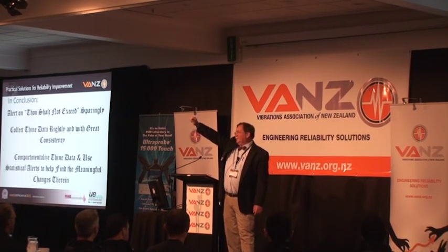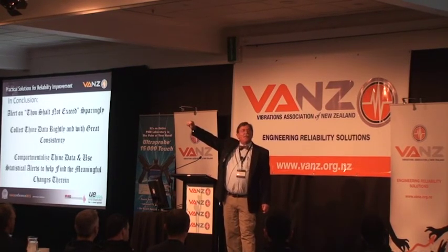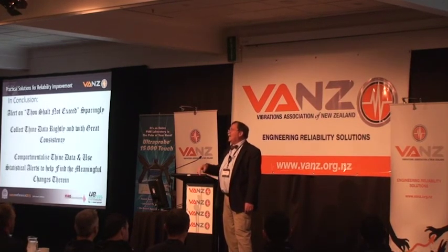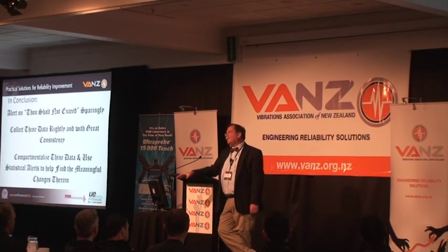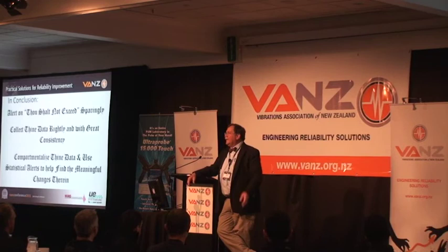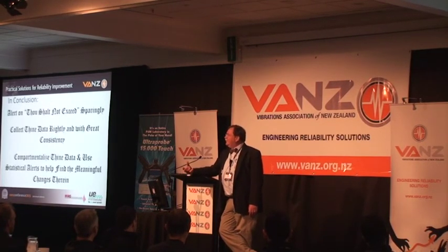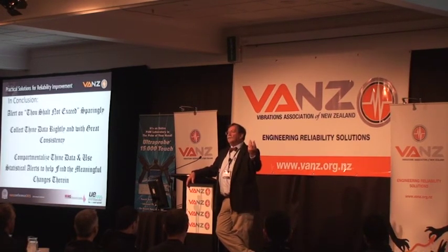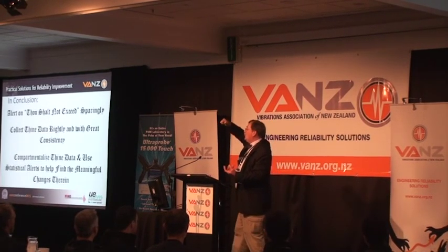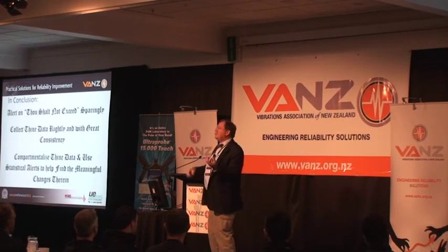There's a clue here. He put the wrong stuff back in to replenish what he had taken out. At that time, the plant had no really good control over what lubricant went in. Let me back up. They had good control of what lubricant would go into what machine if they were going to draw it all out and replenish the whole thing. But they really didn't have the appropriate training and controls in place to make sure that when you draw a small sample out and go to replenish it, you put the same stuff in that you just took out.